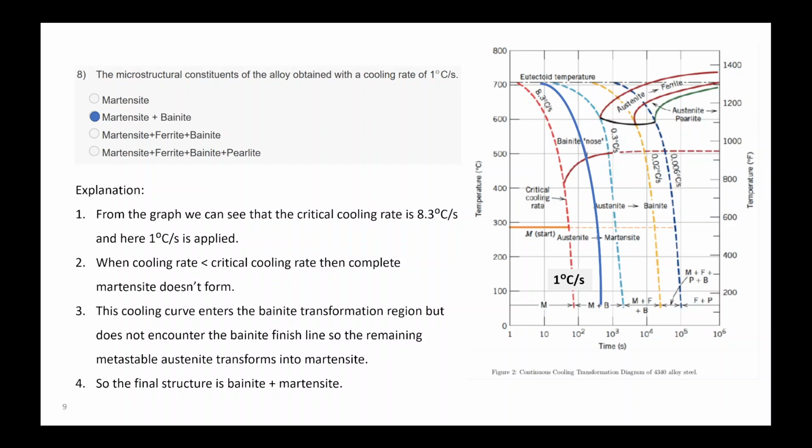If you are measuring the density of dislocations in your material, then you are measuring how many dislocations there are per inch square or like that. Then if you are applying a particular plastic deformation on a material, then a dislocation can generate from a grain boundary, and it can go into the sink as well, become a part of a grain boundary.